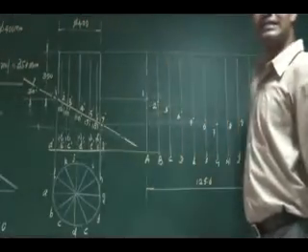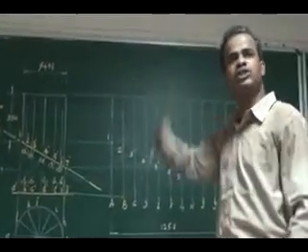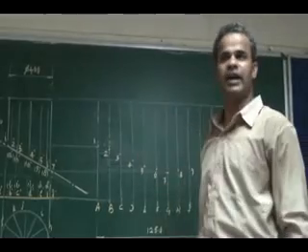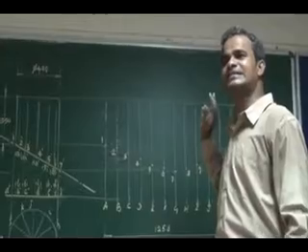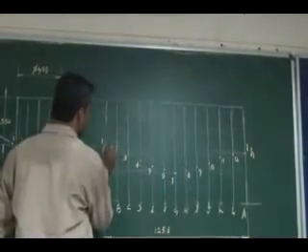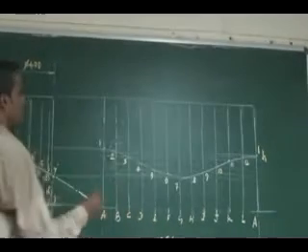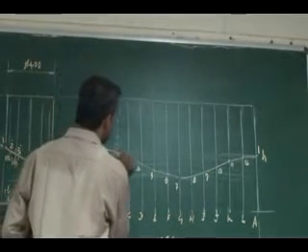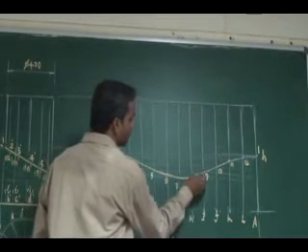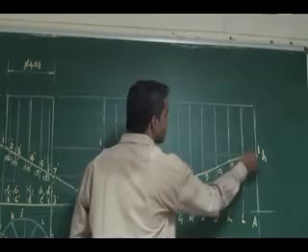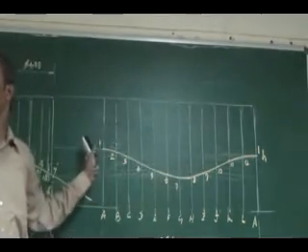Since it is the cutting points of a cylinder and cone, it should be joined in your development as a curve. Apart from cylinder and cone, if it is a prism or pyramid, it should be joined as a straight line. Here, using your 2H pencils, try to get a smooth curve first of all. I will get a curve like this. See here, I can join the curve like this.